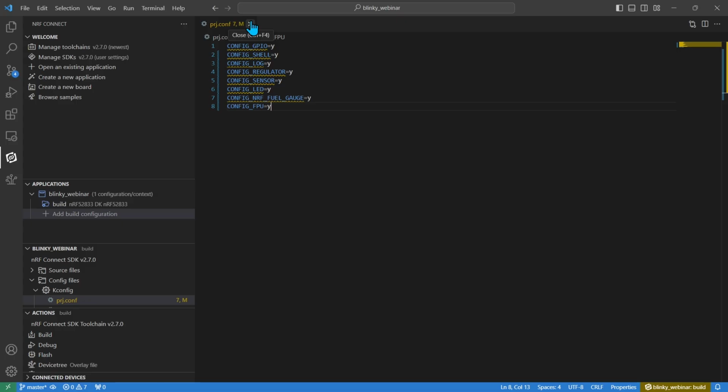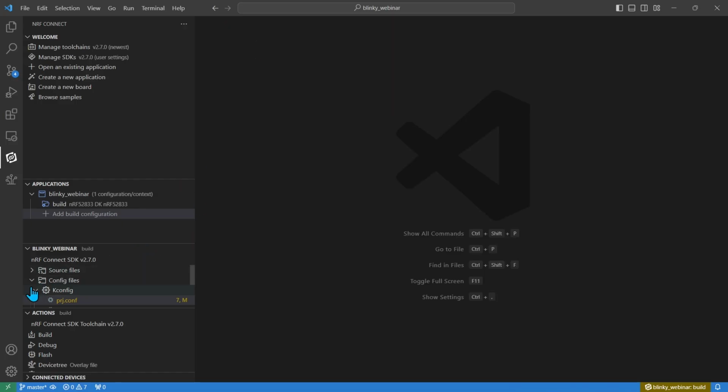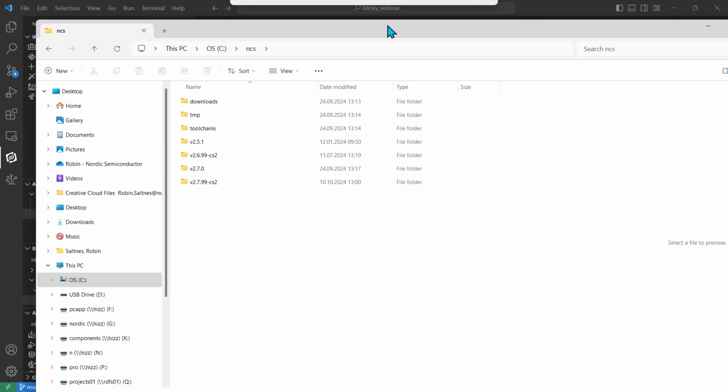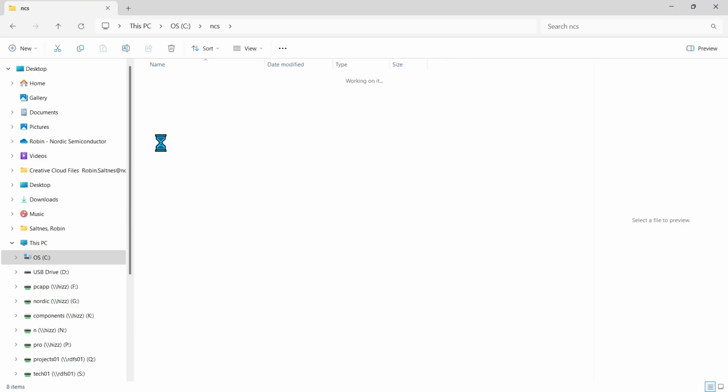And we still haven't done anything to our main C files or any of the files in the project related to the application's runtime operation. So first of all, we will cheat a little bit. So we will go into our nRF Connect SDK source folder, and we will look at a sample called fuel gauge. So here's my nRF Connect SDK folder 2.0, which is what we're on.